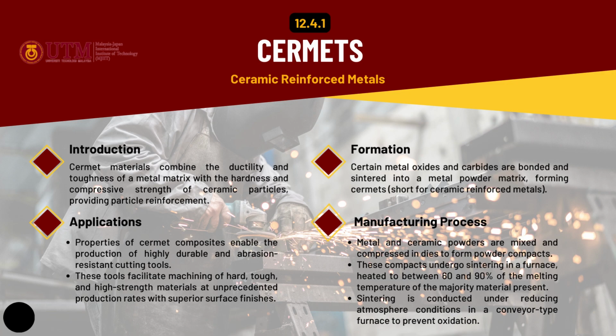12.4.1 Cermet, which is a short form for ceramic reinforced metals. Introduction. Cermets combine the ductility and toughness of a metal matrix with the hardness and compressive strength of ceramic particles, providing particle reinforcement.